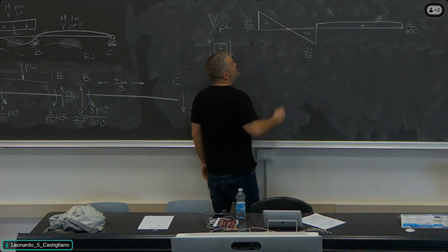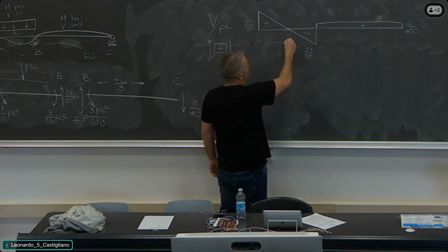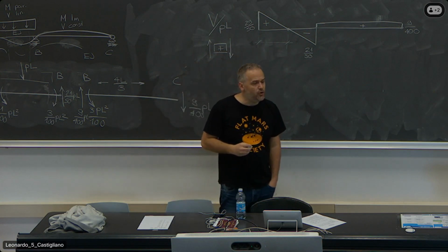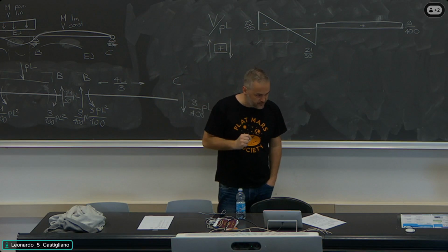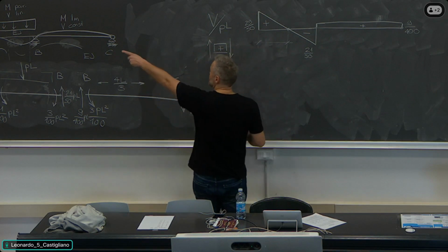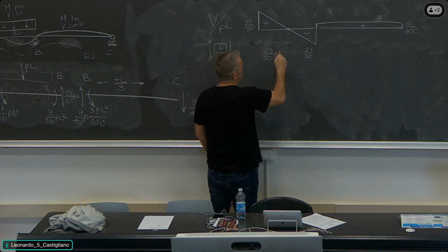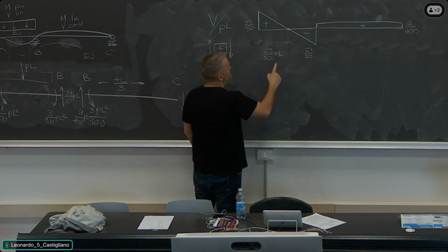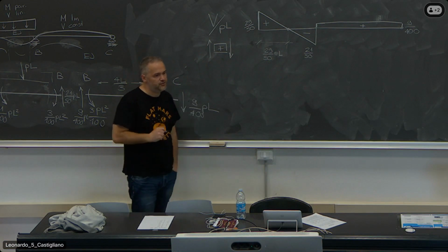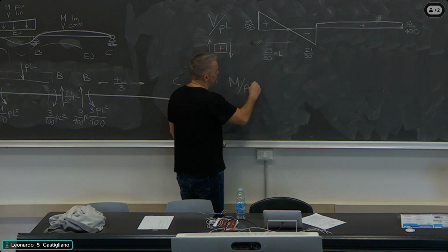What is relevant again at this diagram? Well, what is relevant is the point where the shear force is 0. Why? Because where the shear force is 0, the bending moment will attain a maximum value. Where is it 0? If this is 29/50 and the load applied is P, this is 29/50 L. So, a little bit further than midspan, you have the value of shear force which is equal to 0. Now, to the bending moment, which I'm going to draw in the scale PL square.